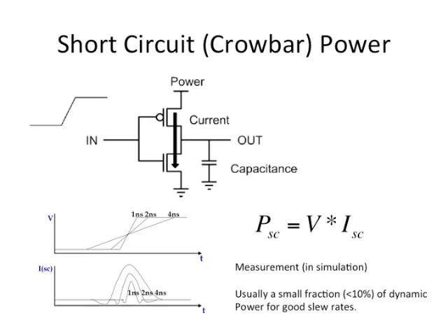So you can measure the current. There are various ways you can measure the total current drawn from the power supply, multiple different ways to get to this number. Now it's a little tricky to get this number very accurately, because you have all these Miller capacitances, etc. But it turns out that number is actually pretty small.